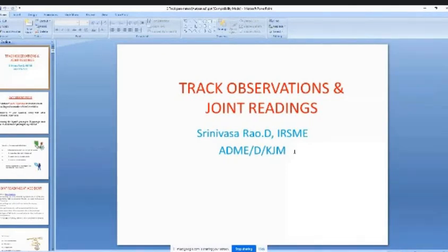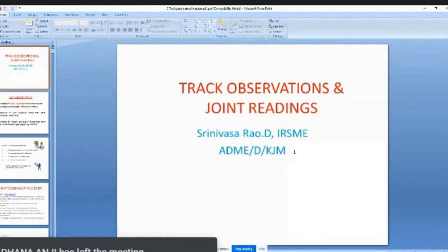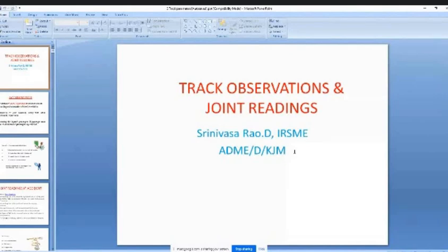Okay, still more will come. So that is why, the reasons we were searching for 20 years back, one SSE would look for a slack gauge, that may be the problem for this derailment. Now those slack gauges are not coming up, because they have changed to PSC sleepers. So gauge widening is an unusual thing that will not happen. Now you have to look for new reasons for derailments, new problems for track maintenance. That way you have to think, not the old pattern.